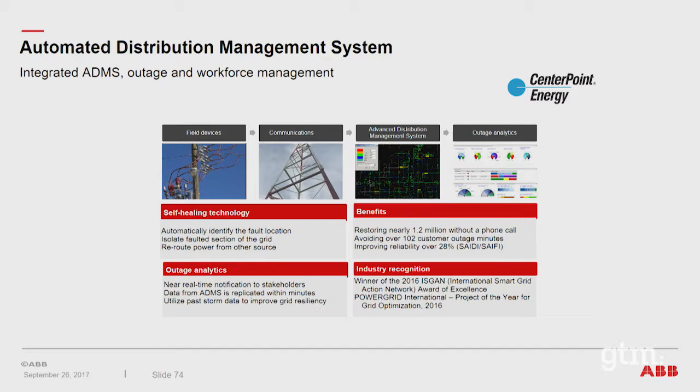It's a self-healing technology system, meaning that the system takes real-time measurements, detects when there is a particular outage, restores the system by isolating the outage, and automatically dispatches a crew, taking into consideration work management applications and asset management applications. The system was thoroughly tested in the last Harvey interaction.